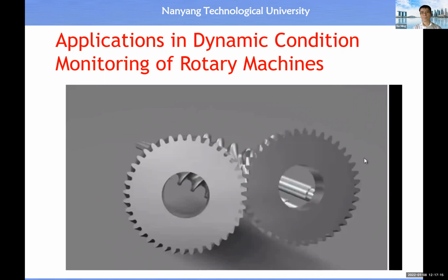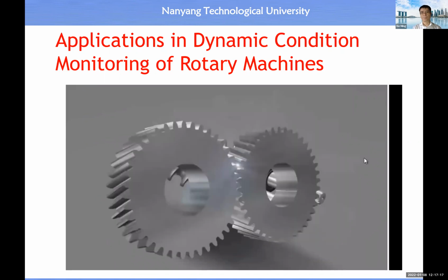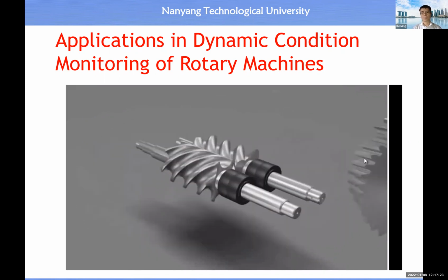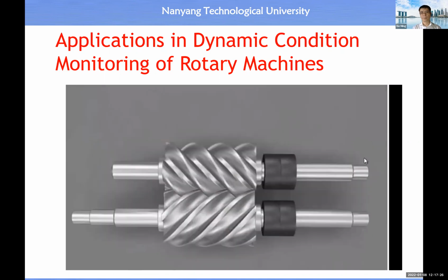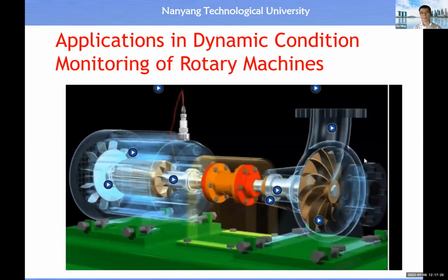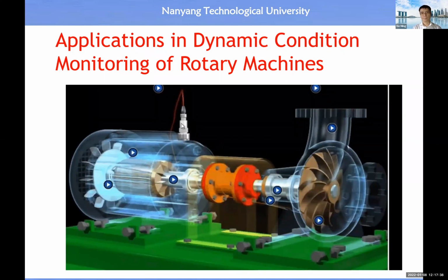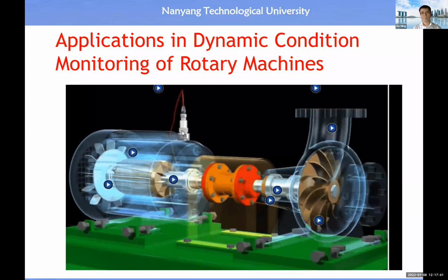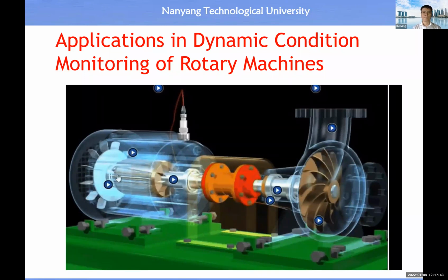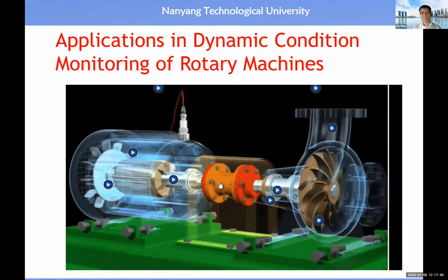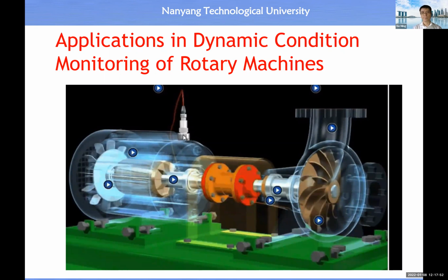Same goes with gears, whether they're timing gears or inside a gearbox. Are they aligned? Are they lubricated? Is there damage to the teeth anywhere? Whatever the case may be, vibration analysis lets us look inside the machine. Now, in this case, we've got the motor driving a pump and a vibration sensor sitting up on top. I'll explain a bit more about that in just a moment. But you may first imagine that all the vibration is transmitted along and goes up to this point, and maybe from this side as well. And that's one of the things I'll mention a bit more about in a moment, just where is the vibration coming from and how's it getting to that sensor.